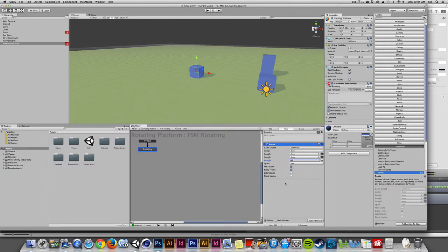And what I'll do is I'll build a little wait function down here at the end that says wait 2 seconds, which should cause this to arrive at 90 degrees. And then we'll pass this to a different action. So I have my transform action worked out, so I'm rotating 45 degrees in the self space per second.